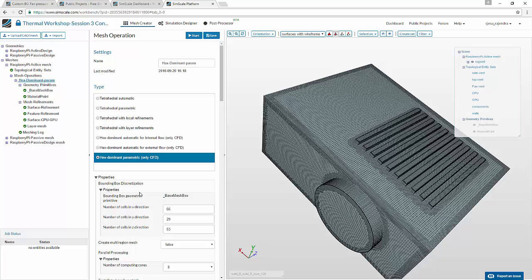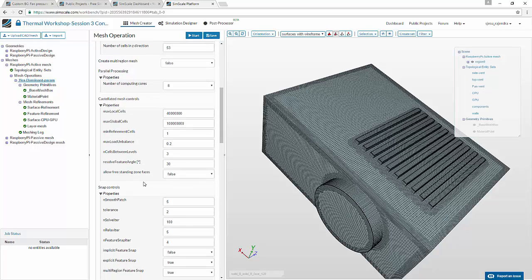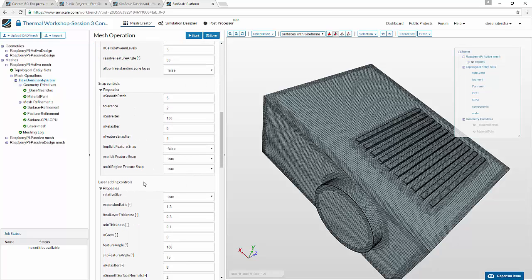When you go for level 1 refinement, you say in place of having one cell, I should have 3 cells. So that is going to be level 1 refinement. Level 2 refinement would be 3 to the power 2, so instead of having 3 cells in level 1, we have 9 cells in level 2. That's how it goes on, and it keeps on going. In general, we get a higher number of cells wherever we require, or wherever the refinement is supposed to be.